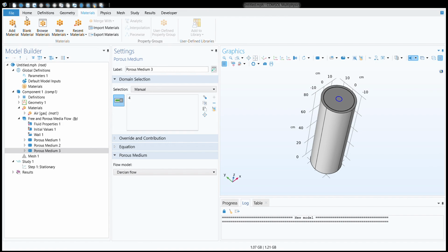Now we can export. We have to export the geometry. To export the geometry, click on the geometry, right click and click on export. After clicking on export, we have to choose a file name. We can name it as dome, and export entire finalized geometry compatible with anything.